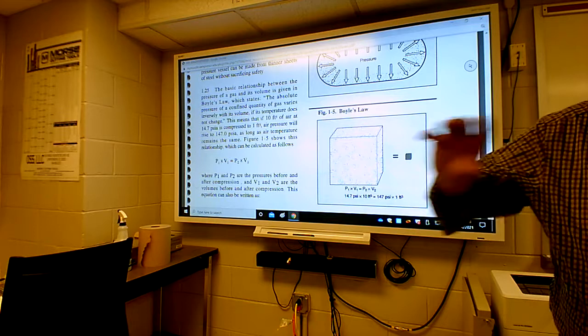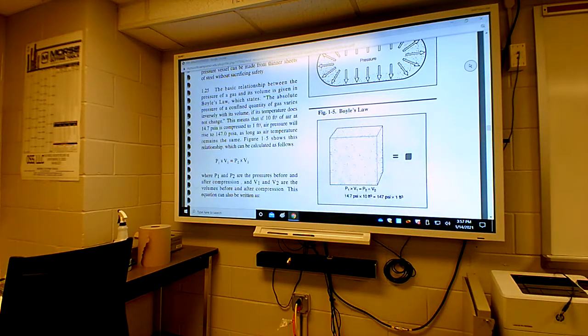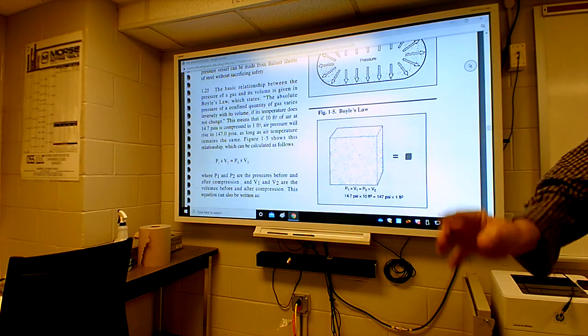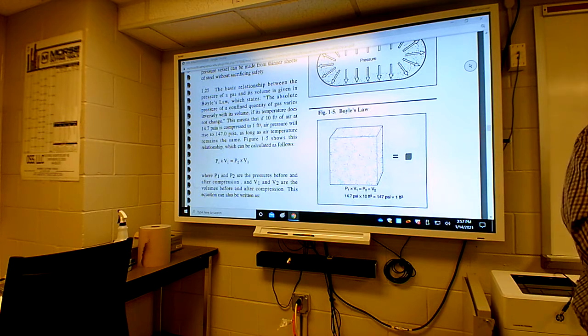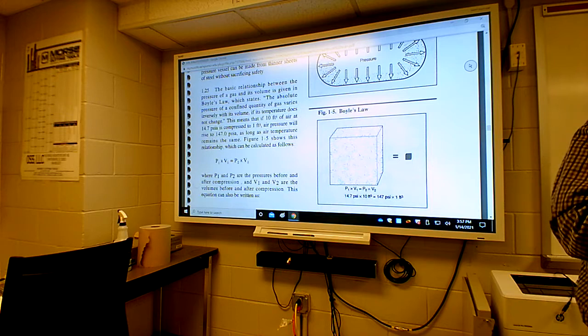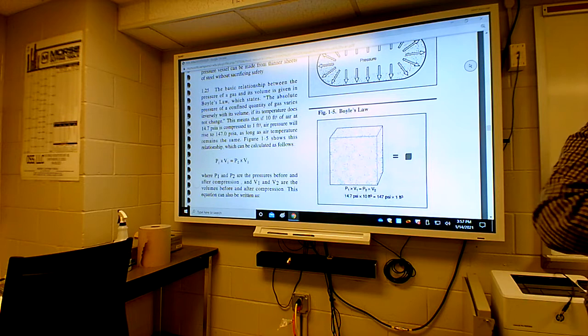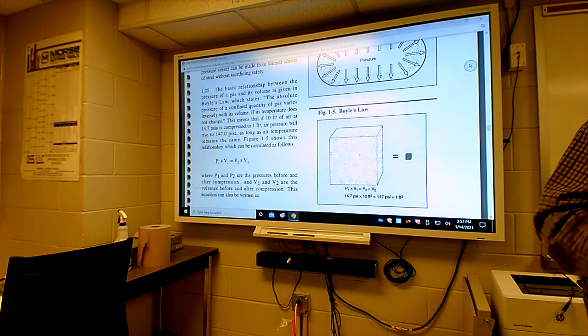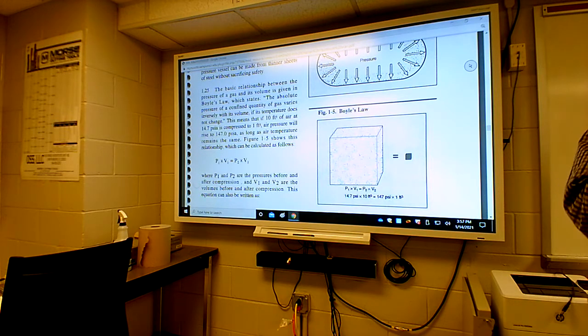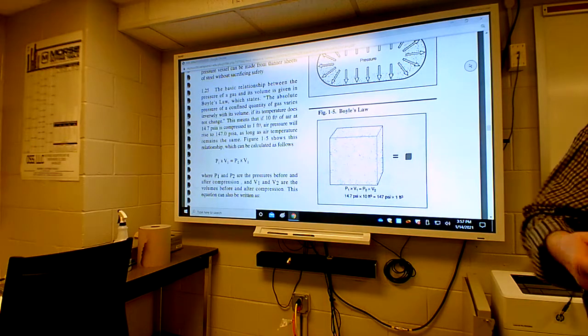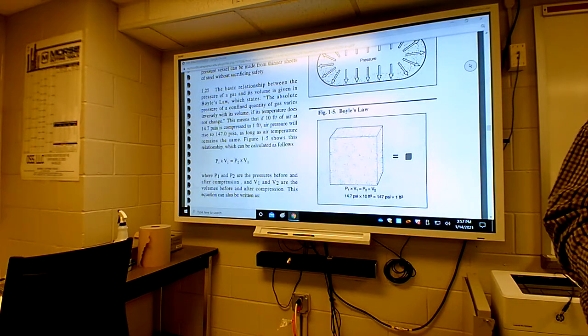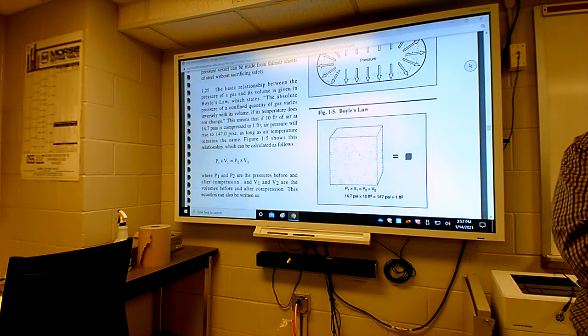The air compressor has an intake stroke where it pulls air in from the atmosphere. Then when it compresses, it's changing the volume, the area of the inside of the piston where it's compressing the air. When you squeeze that air, what happens to the pressure? It goes up. When the piston compresses it, the pressure is going to go up. That's how a reciprocating compressor does it, by compacting that air.